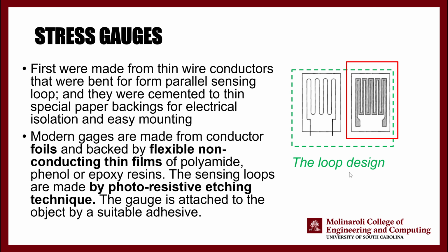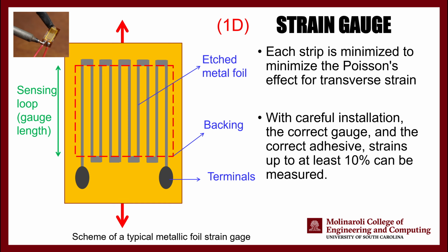which is going to change the resistance of this electrical system and eventually change the electric potential or electric current that your computer is reading. And based on that change in the resistance of the circuit, you are going to see a strain. We have a relationship that relates a strain to the electrical resistance of your circuitry. Okay.